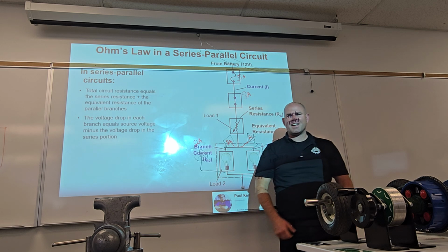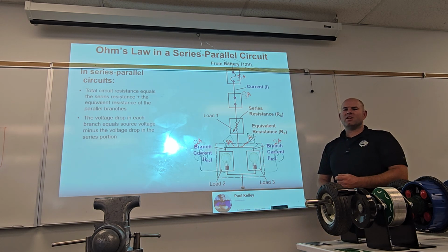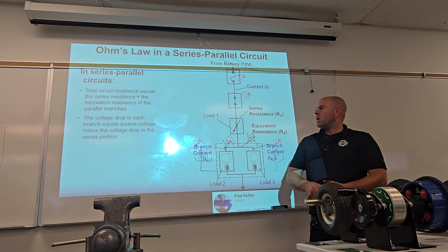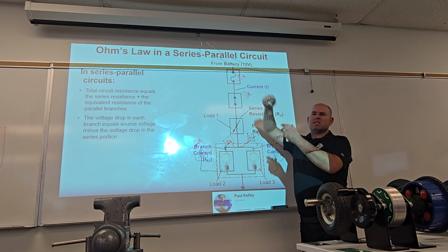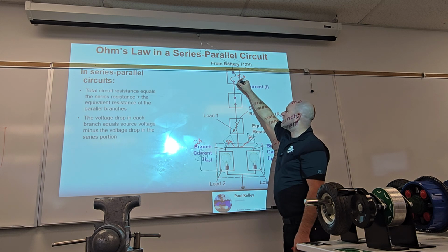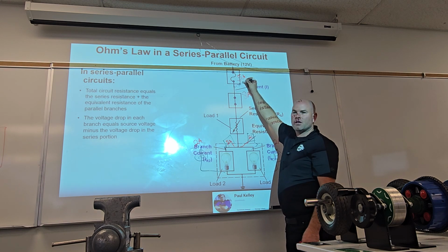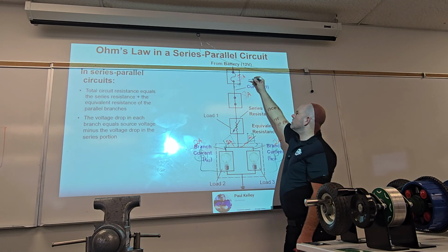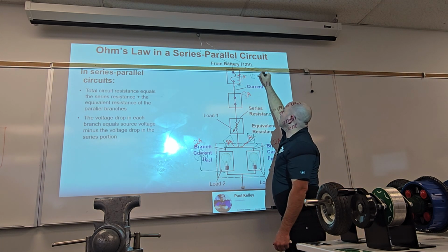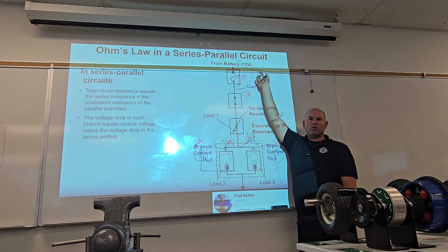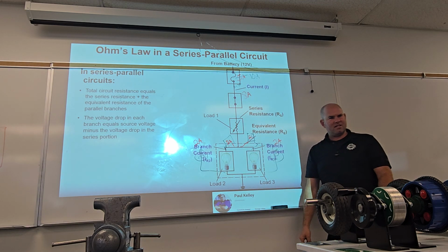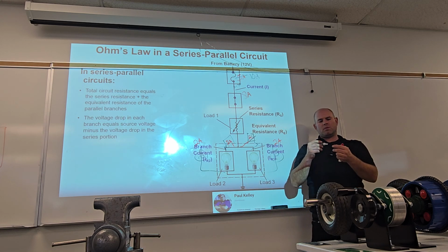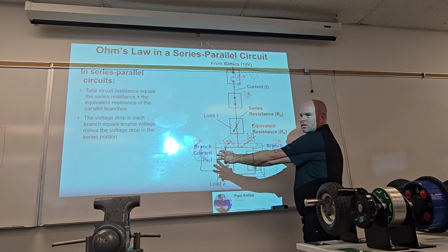Don't you dare say that. No, we definitely do not put a bigger fuse in. Because remember, if the fuse is 5 amps, this wire's probably good for 6 amps, 7 amps maybe, not 8. You know what I'm saying? So if now you have a 10 amp fuse in there, you're like, oh, I got an upgrade. I upgraded to the red fuse. The red fuse is high performance. Exactly. So now we're tying it back to what we covered before. That's why something like this is kind of critical.